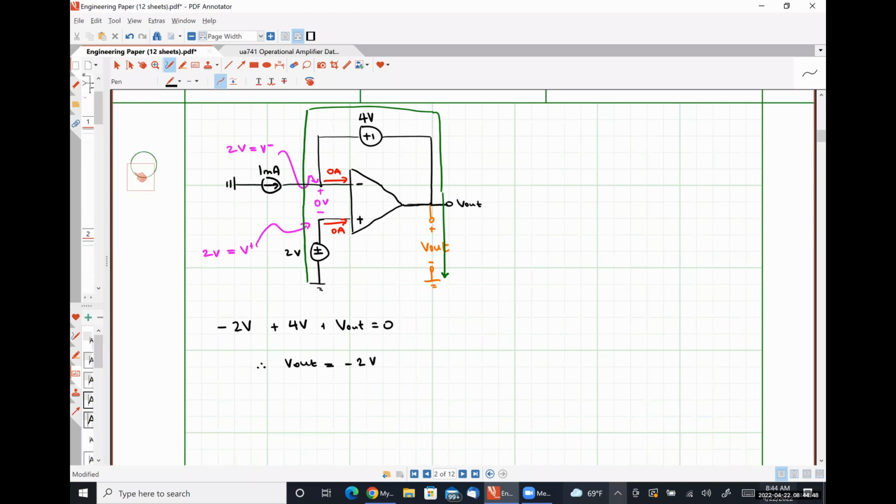So anytime we have a voltage source in the feedback loop, that is the Kirchhoff's voltage law path I would suggest that you take. It's going to be the easiest one to figure out. Even if there's a voltage source and a resistor or something like that connected to the inverting input terminal, I would still suggest that you take this specific path. Mainly because it most closely aligns with the 3-step procedure that I've tried to introduce to help you guys solve these things systematically.